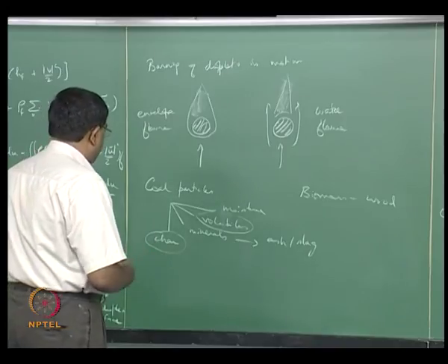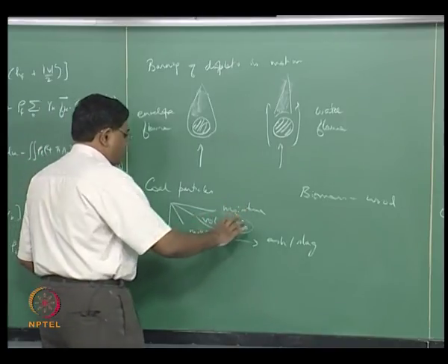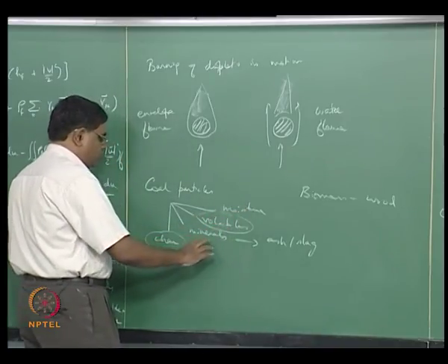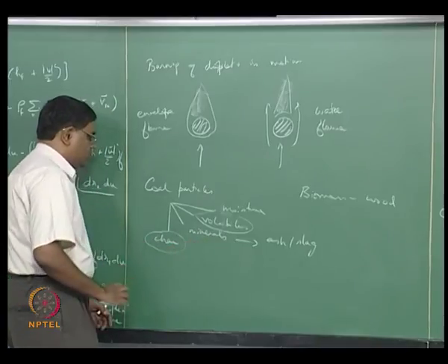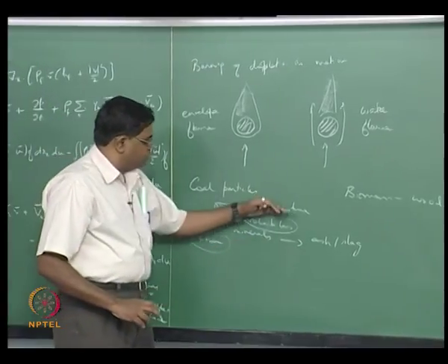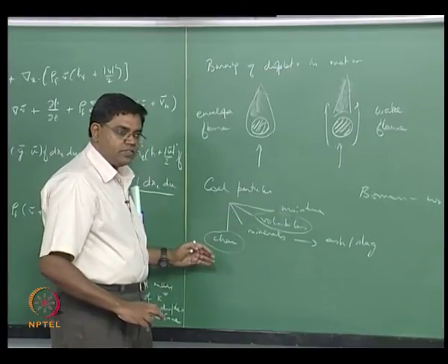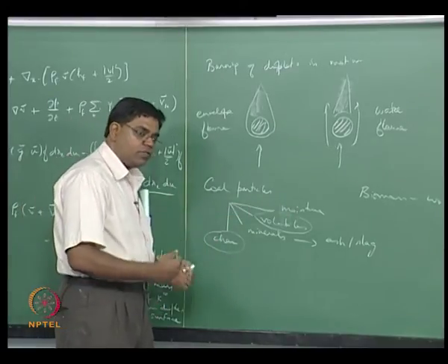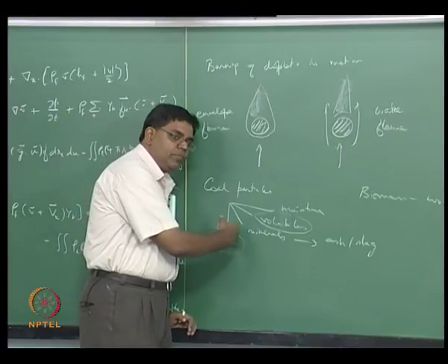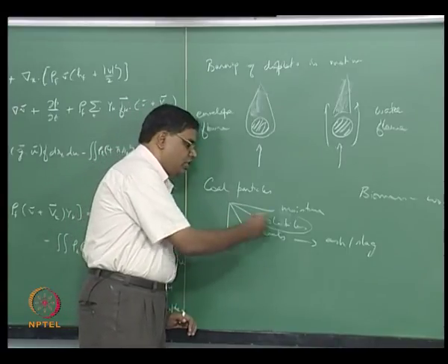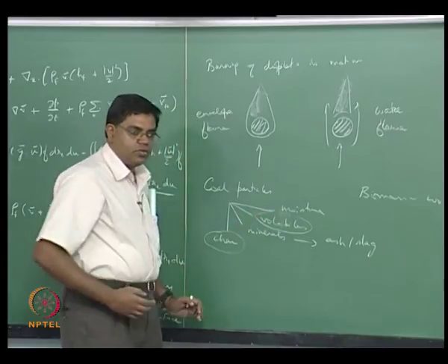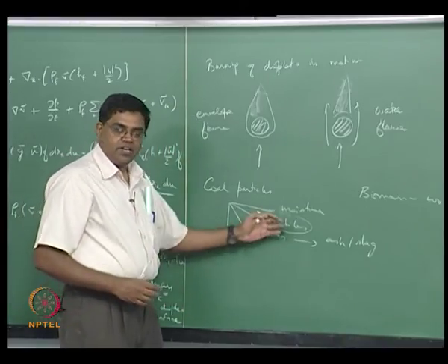So typically again you have to characterize what's the moisture content, what's the volatiles content, what is the minerals content, what is the char content. So doing this kind of thing is what's called a proximate analysis, trying to find out what are the different percentages of these different things, and then in turn you also have to find out what is the elemental composition of the energy containing constituents, and that is what is called the ultimate analysis, right.